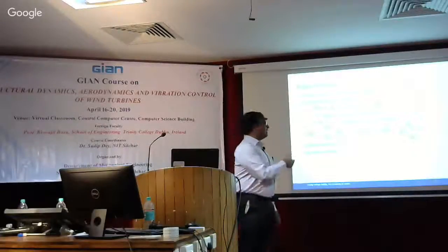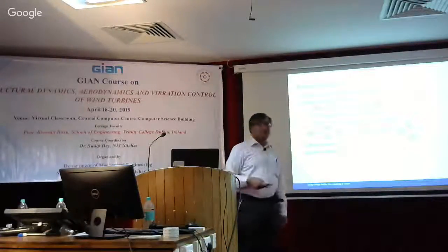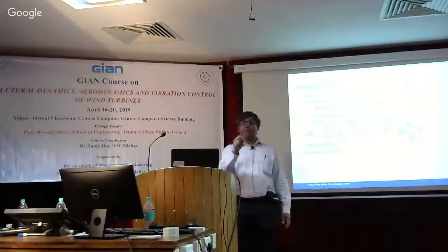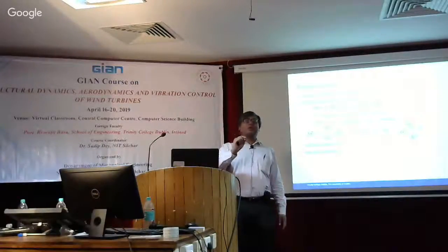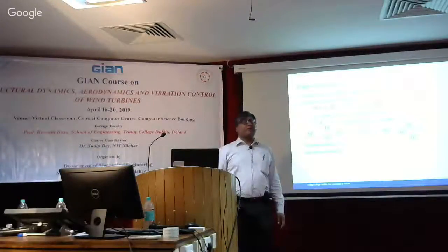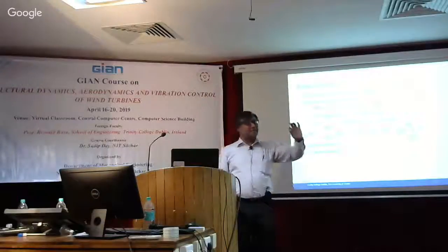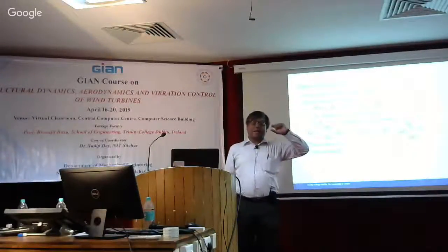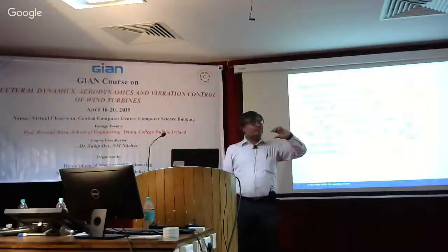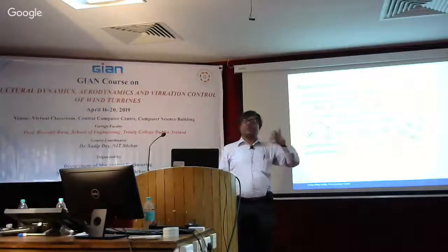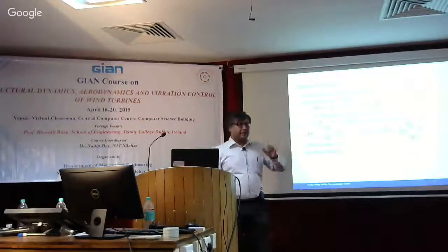Then when I take it on the left hand side, anyway this was very small, damping was not there almost, so that's why we wanted to put some damping. Because you know the difference between zero, no damping, and slight damping is enormous. Because with zero damping, you have infinite response. With little bit of damping, you have the whole thing under control. So at low value of damping, the sensitivity is very high. And when the damping is relatively high, 2, 3, 4%, beyond that, it doesn't matter whether it's 5 or 10%. So it's already taken care of.